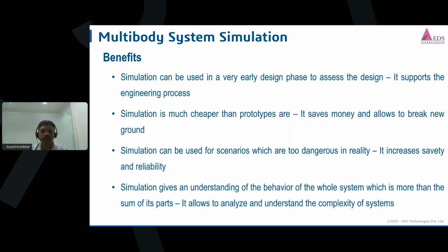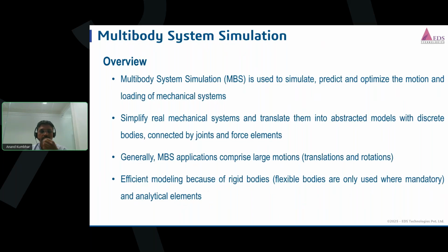So, previous. MBS applications generally involve large motions, translations and rotations. The components often undergo large movements, including significant translations and rotations. MBS formulations are specifically designed to handle large nonlinear motions accurately. Then there is efficient modeling using rigid bodies and analytical elements: modeling most components as rigid bodies, which reduces the number of degrees of freedom, and using flexible bodies only where deformation significantly affects system behavior.